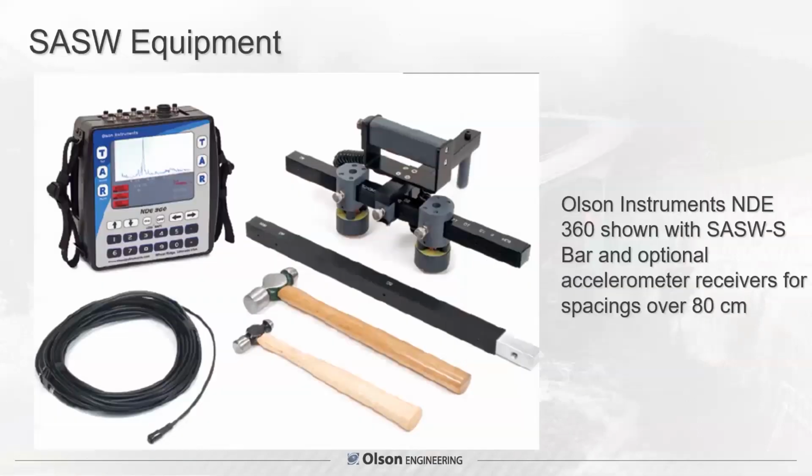This shows the SASW equipment, so you can see a better picture of it. This bar has displacement transducers. That's a similar design as what is in the impact echo testing equipment for point by point. You can spread those from as close as 6 centimeters apart up to 80 centimeters by adding this bar on the end. And you can use small to larger hammers.